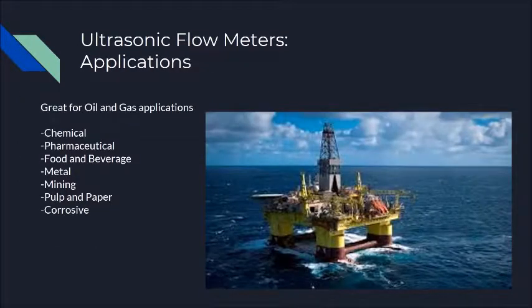As far as applications go, it's more common in oil and or gas applications. You'll see that some of the other less common uses are similar between the two. Like we have chemical, food and beverage, pulp and paper, it's shared between the two. A couple differences: it's good for corrosive, because the ultrasonic relies more on the particulates in the fluid, so using a corrosive or chemical fluid, something that isn't distilled or clear, tends to be more applicable.